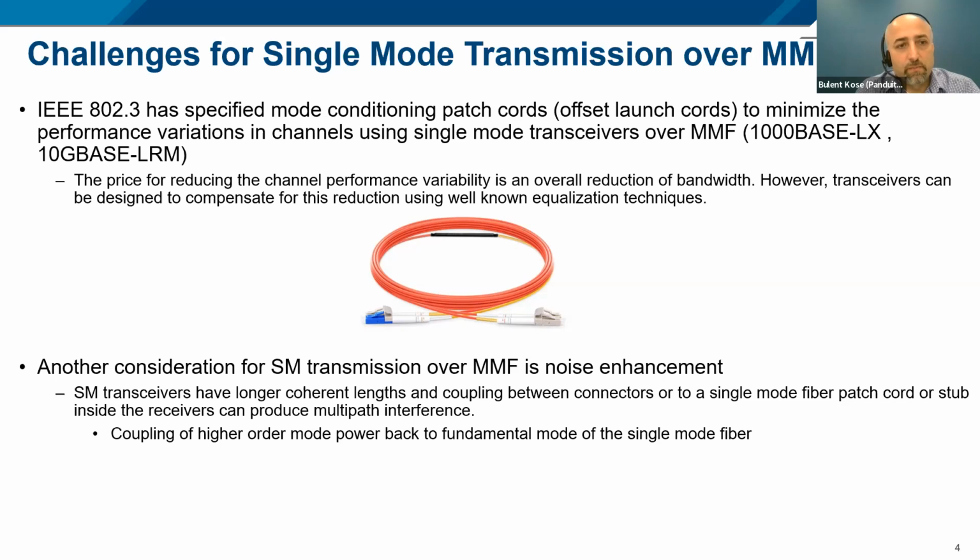Another area of concern or challenge for single mode over multimode is the mode coupling due to the connectors. Any offsets increase the noise because this is phase sensitive.